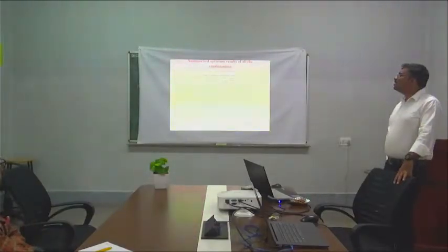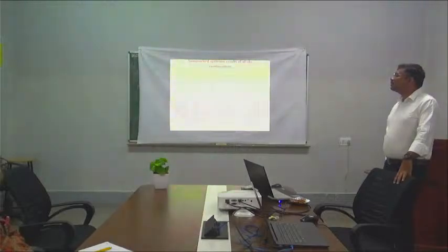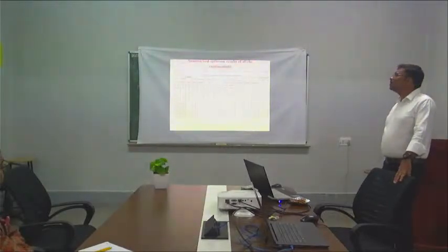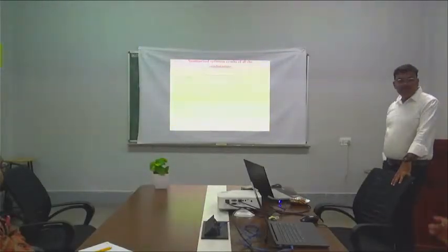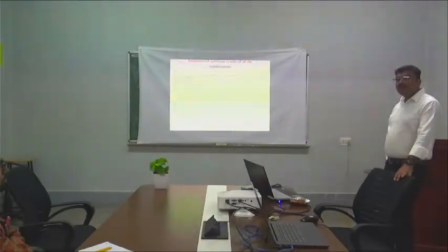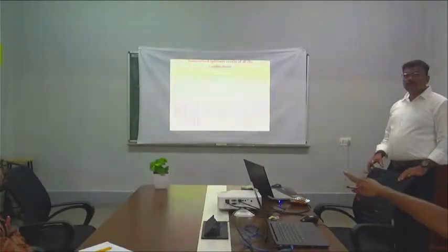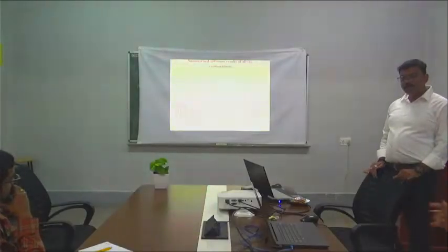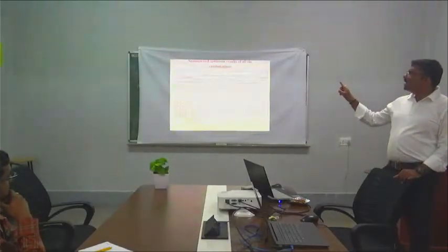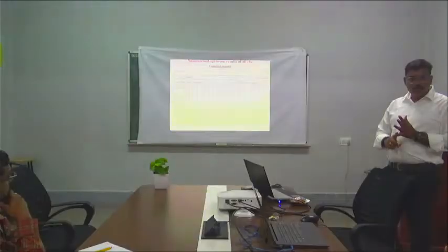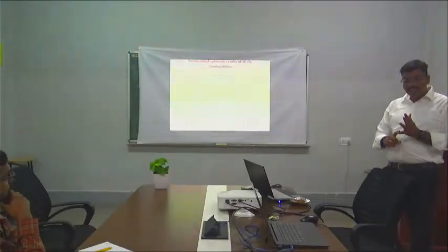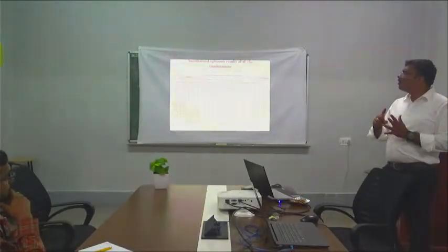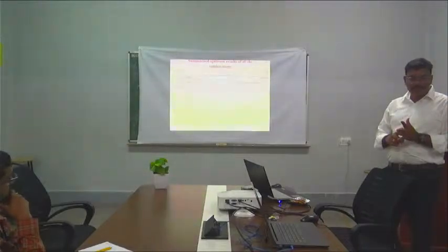We conclude that with PV, wind, biomass, without DG, with some battery storage, 74 kilowatt of battery storage, and with the converter rating of the output of each source, how are we deciding, using any optimization, the output of each source? Like PV rating in the first case 60, wind 20, how are we getting those values? The sizing is done by using the optimization algorithm, the Homer optimization algorithm. Sizing 60 is decided by the algorithm, 20 is decided by the algorithm, 40 is decided by the algorithm.